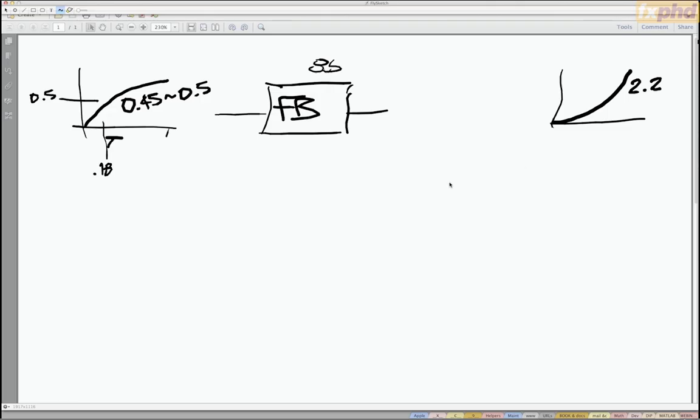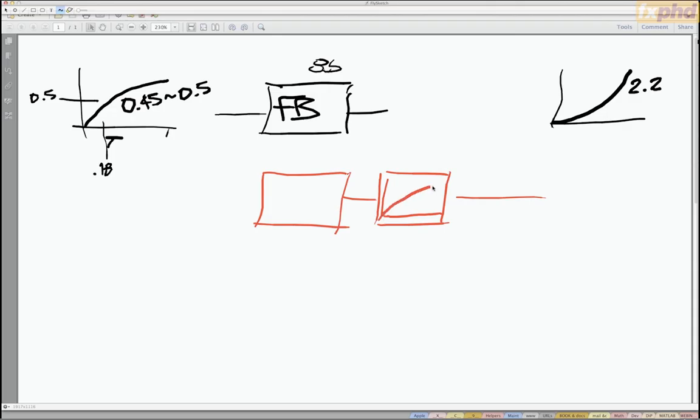Now, the old Macintosh situation was that Mac had a frame buffer as well, but for reasons that aren't really perfectly well understood, Apple, instead of just doing nothing in that lookup table and being compatible with the rest of the industry, instead loaded a very subtle curve into that lookup table. It was 1/1.45.